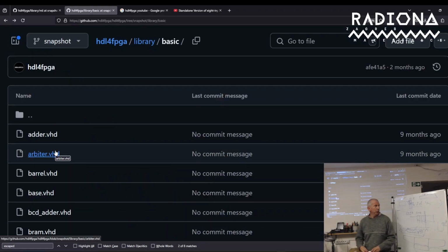So probably maybe I delay this. I don't know where I'm delaying it. And on the others, I think I'm delaying these 4 bytes because finally to make the commit I have to check if the CRC is valid. And by delaying this, you won't pay much of a price.